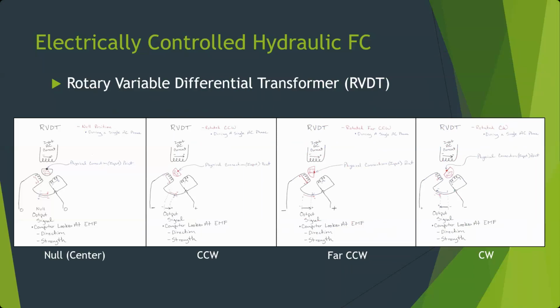In fact, when I was teaching people to run taxi, they would be in the left seat, I would be in the right seat. The circuit breaker for the nose wheel steering system was right down by my knee. We'd be going along nice and happy, and I'd just kind of reach down and pop. They wouldn't even know it. But it allowed me to run a scenario as part of training where, okay, now get us back to the hangar without having nose wheel steering. Basically castering, like if you've ever flown in the Cirrus, they have a castering nose wheel.